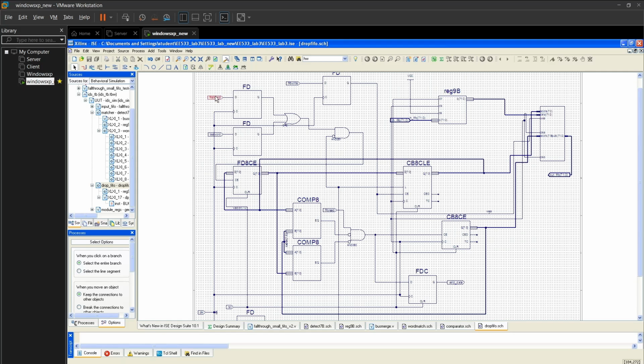And this last word and first word are for the case where, if it's a first word, we shouldn't read from them at that time. So for that, we have this block, and similarly for last word. This is to prevent a case in which we are reading or writing the first or last word, which is an error. So for that, we are designing a specific last word or first word. Then it should be loaded here to reset the whole FIFO for write address, and similarly to have a connection for read address as well.